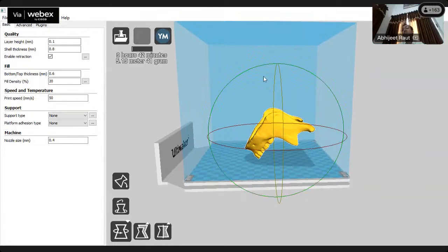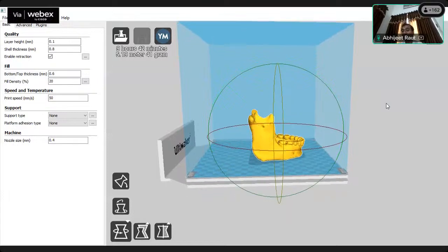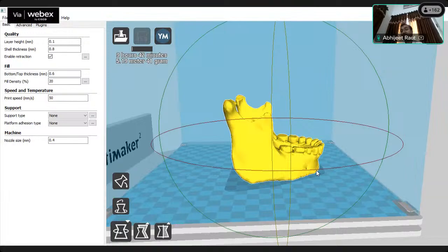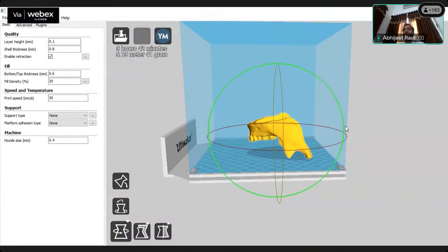You need to place your particular geometry, how you are going to orient it, not only to get better accuracy. Why am I saying this? Because whenever there is a support, if this particular area is our targeted area, we can't keep the position like this. Why? Because it will take the support.